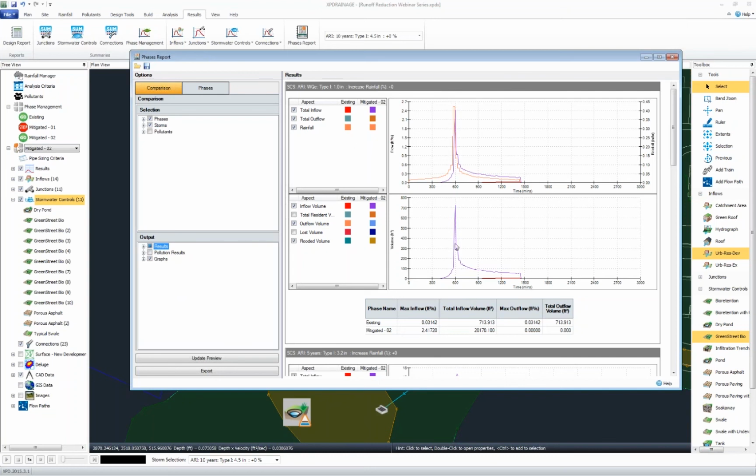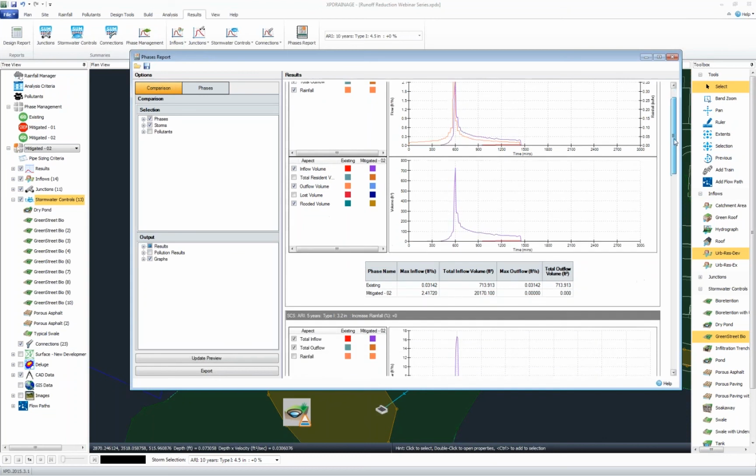So great. In the water quality event, in the existing event, we have outflow from our model. Okay, well, we're going to say in the existing phase, the water quality event, we're going to fully contain that, and that's what we're doing here, right? We can see we have 20,000 cubic feet of runoff. That's a little more than 19,000 cubic feet more than we used to have. We're fully containing that because there's no outflow out of our site.